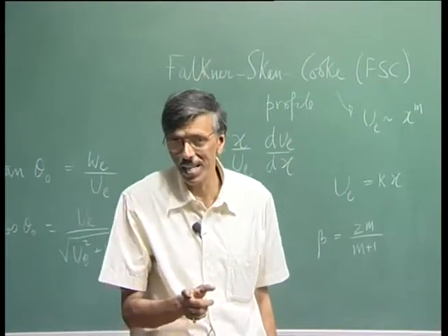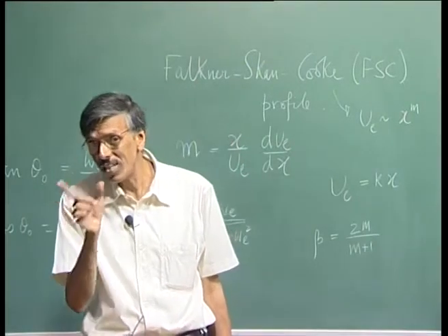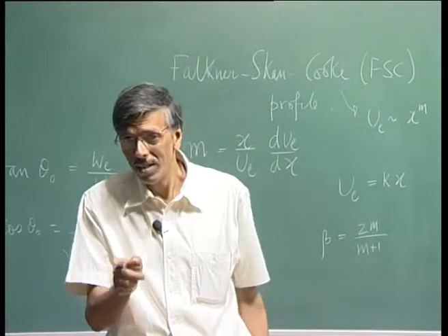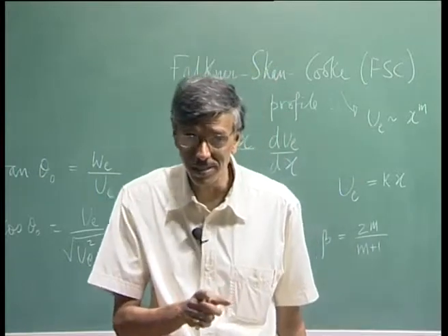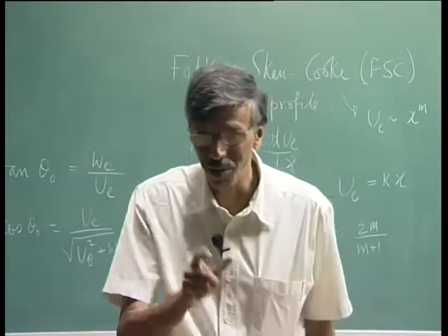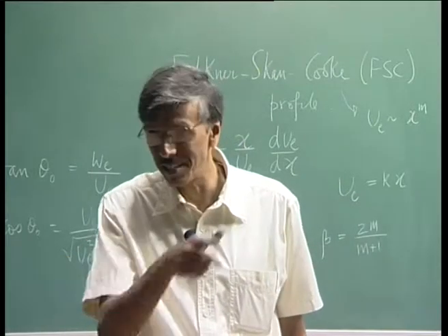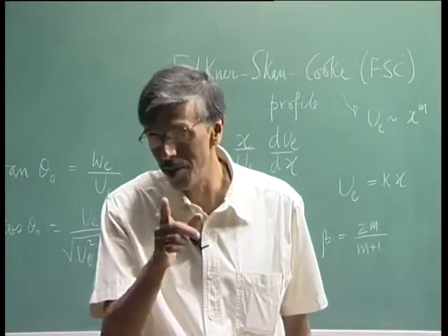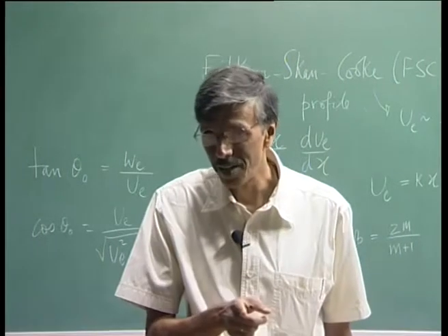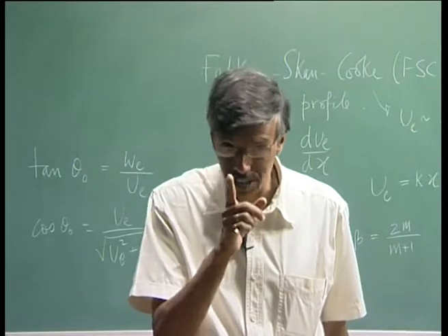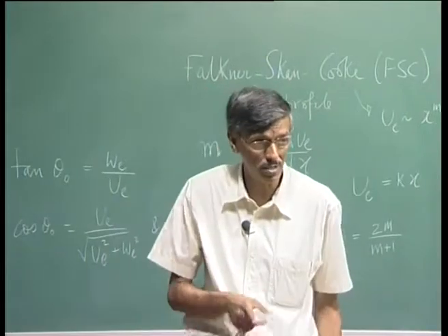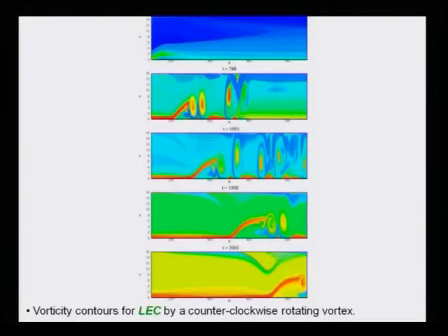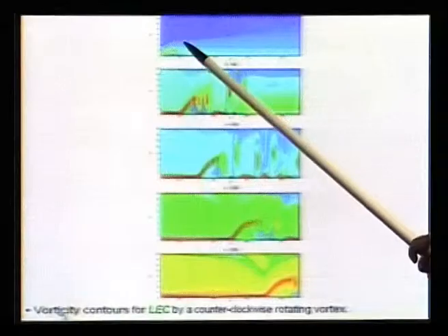And what did we see in the Blasius profile also? That it is selective. It does not happen anywhere but at a fixed location. And what was that fixed location? That is what we are doing through the assignment. We are finding out at different x's the time history of pressure gradient. We will be able to find out why and where it occurs and at what value of C it is the most potent. That is the essence of the assignment that you are doing. What you are going to report back to me is a specific nature of the Blasius boundary layer. Quite unlike here, you will not have that.